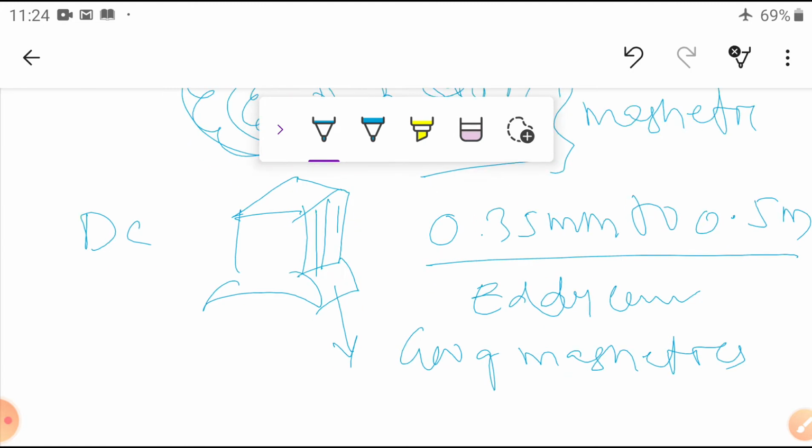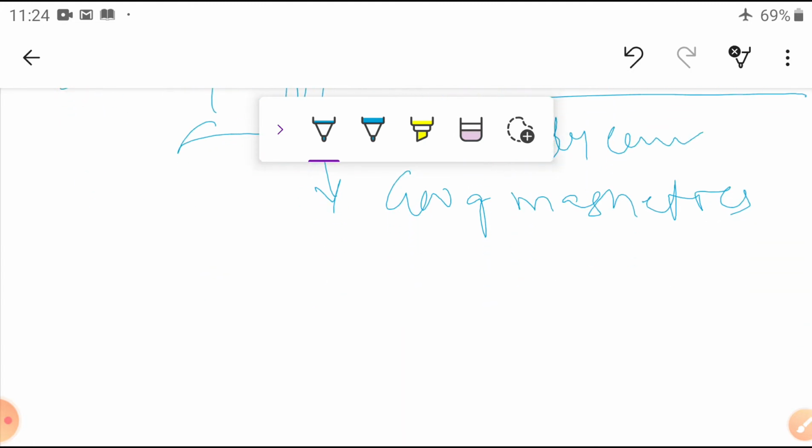What are the good magnetic materials generally used in our electrical field? Here we are going to use soft magnetic materials, generally used in all rotating magnetic machines. The fully processed silicon iron material is one of the topmost materials, silicon ferrous.